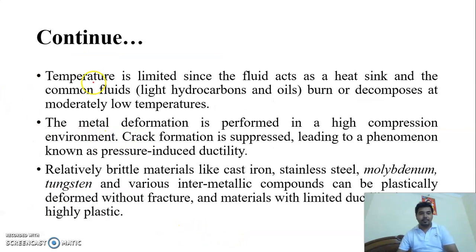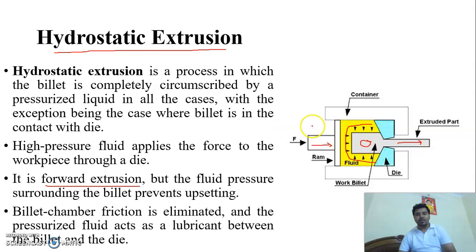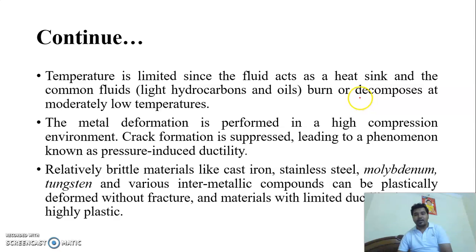Temperature is limited since the fluid acts as a heat sink, and the common fluids burn or decompose at moderately low temperatures. In this process, we have to use cold extrusion. Why? Because if the temperature of the raw material is high, then the fluid will burn or decompose.